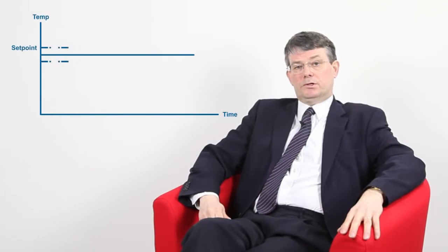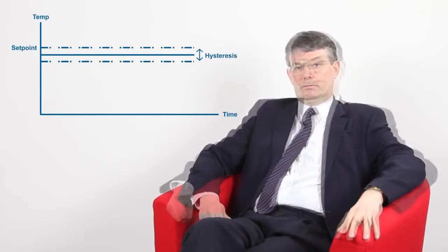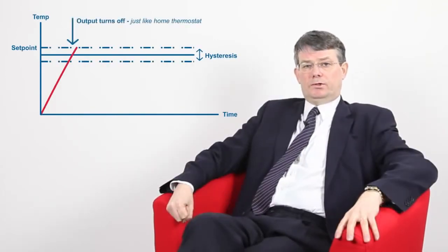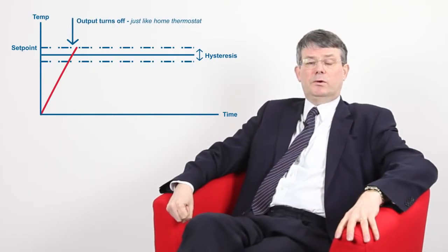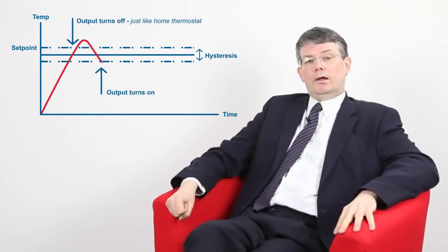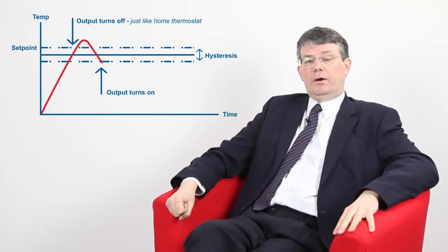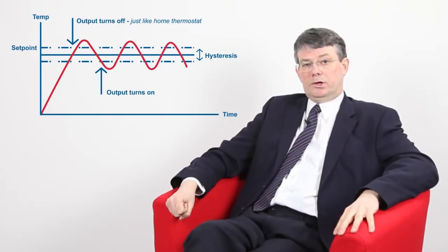We've seen that proportional control will give better stability in the process, so you might wonder why anyone would ever use on-off control. A proportional controller must always be tuned to the process, and this can be a little bit daunting for users. If the process doesn't require a high level of stability, the simplicity of on-off control can sometimes be attractive. Unlike proportional control, on-off control only has as a maximum one parameter to adjust. This is the on-off differential.